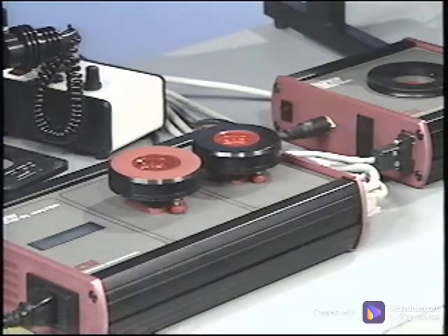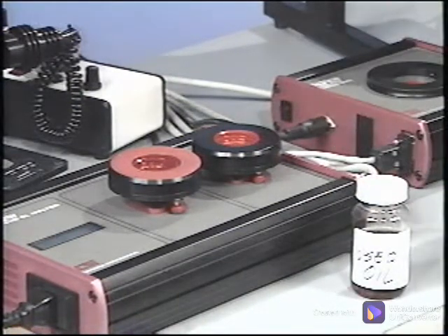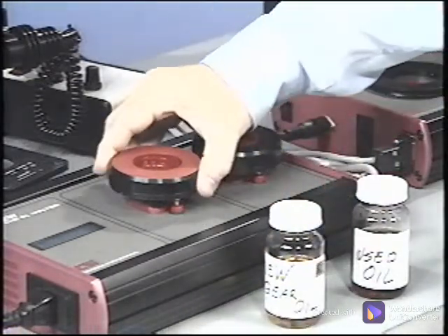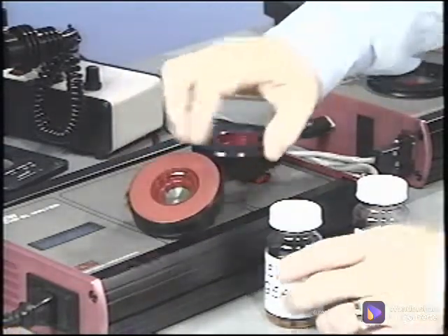To check the oil quality for degradation and any other gross chemical changes, the OilView analyzer compares a used oil sample with a clean oil sample of the same type used in that application. The changes in the oil chemistry are detected capacitively by the OilView sensing grid.